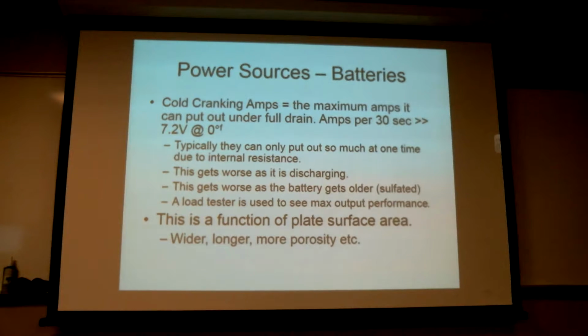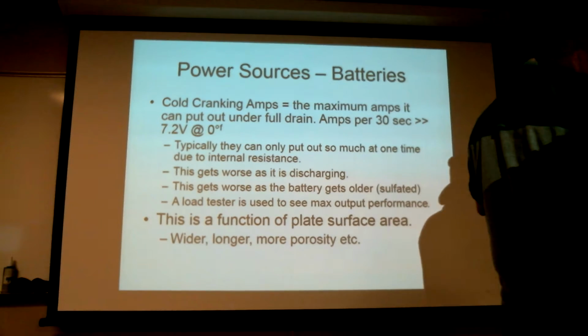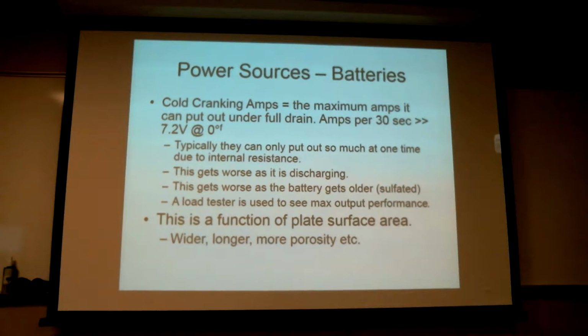The second quality is a characteristic of a battery that's used in a high current application. Cold cranking amps is one way of measuring total maximum output per unit of time. There are other ways of doing it, and that's going to be true of all lead acid batteries. But in a battery that's meant to be a starting battery, it's going to be really important. In a deep cycle battery that puts out a small amount of current, but keeps your light bulb and toaster or whatever you've got on your boat or motorhome running for a long, long time, we don't really care about the cold cranking amps. It still applies, we just don't care about it.